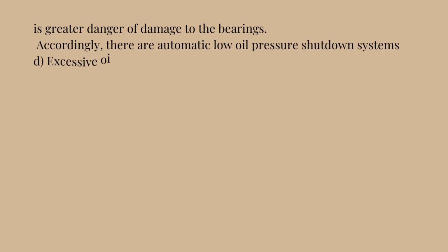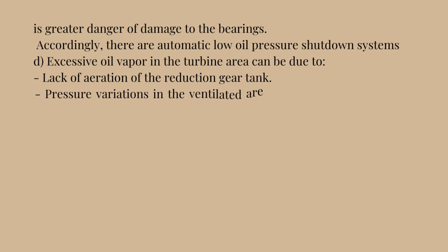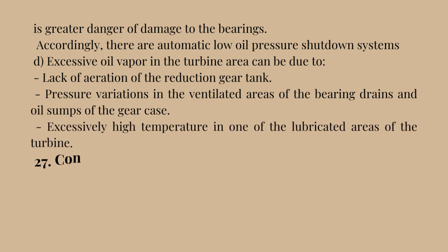D. Excessive oil vapor in the turbine area can be due to lack of aeration of the reduction gear tank, pressure variations in the ventilated areas of the bearing drains and oil sumps of the gear case, or excessively high temperature in one of the lubricated areas of the turbine.